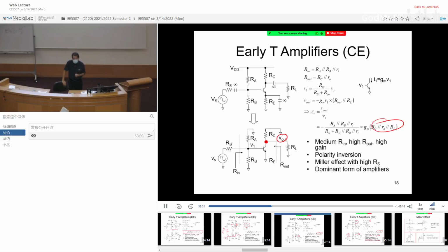First, there is a negative gain. Now here, I need to bring to you, in amplifier terms, negative doesn't mean loss. Okay, amplifier, you have negative, it doesn't mean loss. All it means is phase inversion. If your signal is positive, you end up having negative. If your input is negative, you end up having positive. Everything gets inverted. Okay, but as long as the number is bigger than 1, you have gain. So, polarity inversion.